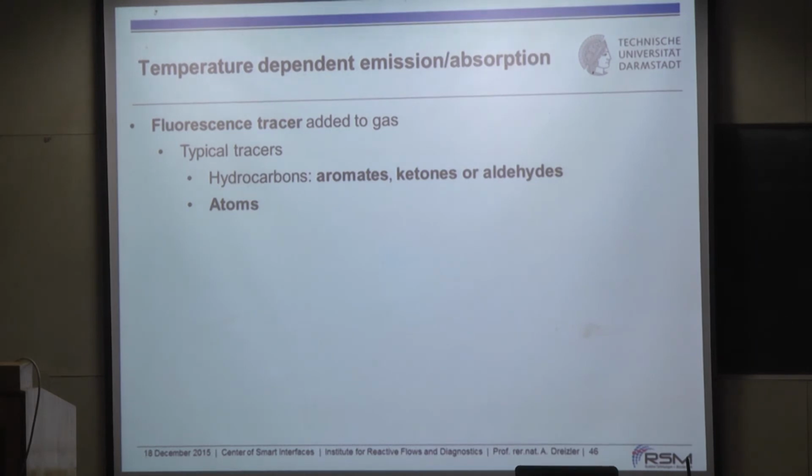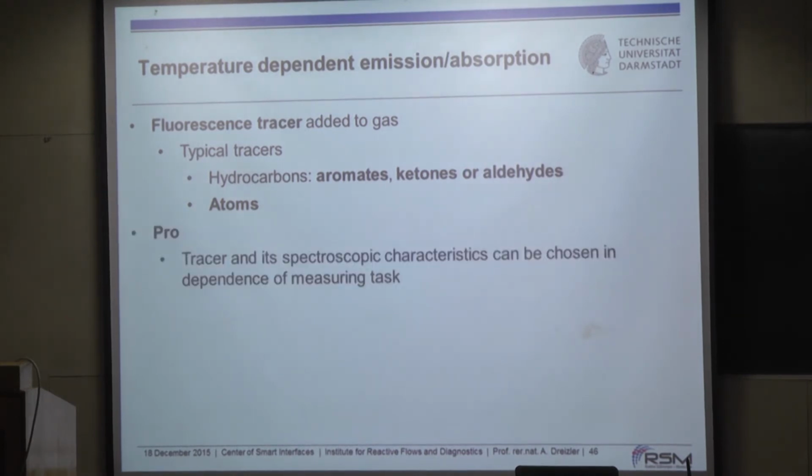Very often that is required in IC engine combustion, for example. That is very important. However, atoms like indium, if they are put like indium chloride into your fuel, are produced only in the flame front. And so those atoms are capable of measuring temperatures only in the exhaust gas. So you see, this is already not the best choice because you have more restrictions than before.